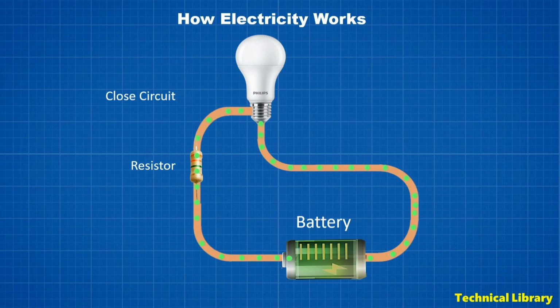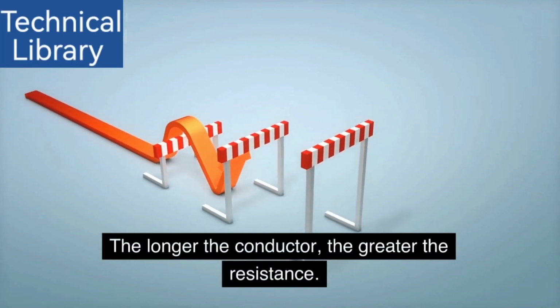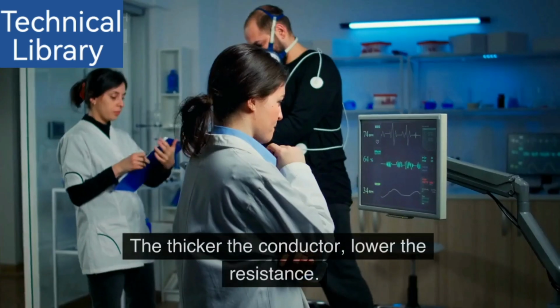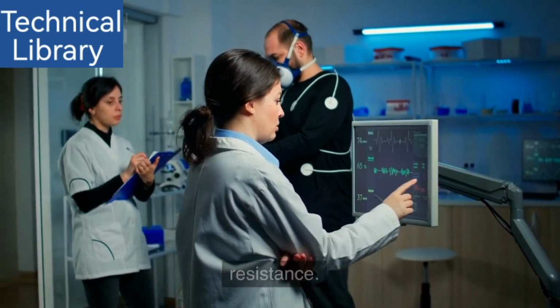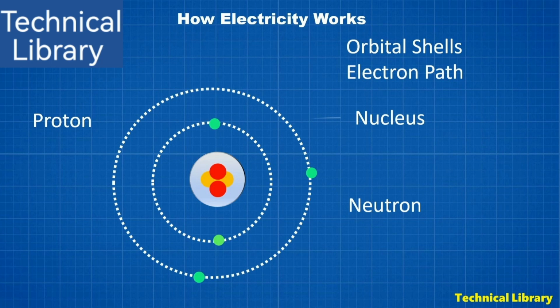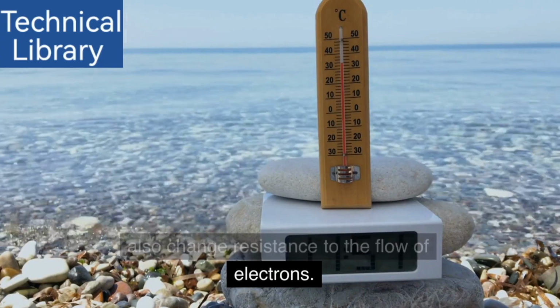Resistance is a restriction to the flow of electrons in a circuit. The conductor which carries the electrons will naturally have some resistance. The longer the conductor, the greater the resistance. The thicker the conductor, the lower the resistance. Resistance to the flow of electrons is different for each material, and the temperature of the material can also change resistance.